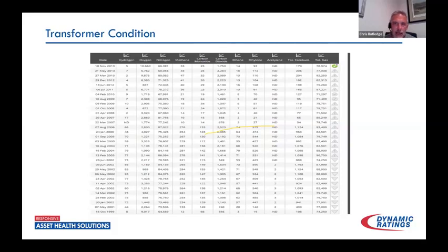And again, I didn't have online monitoring for this unit, but I have a good feeling if I had taken a gas space sample, because I've done it with some other units, you would find that it was quite high, actually. So that was something else to consider. So I think that a hydrogen alarm still would have been very effective in detecting this problem.